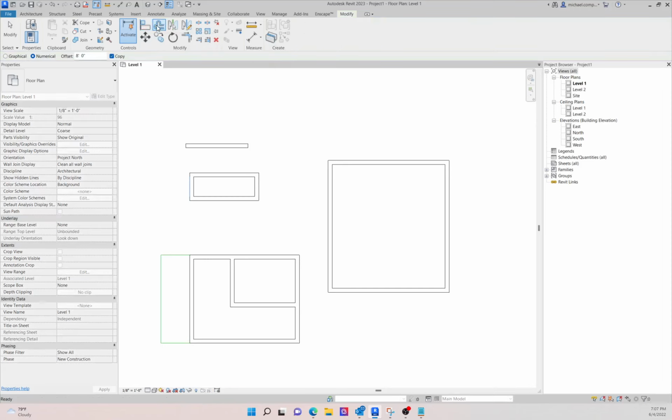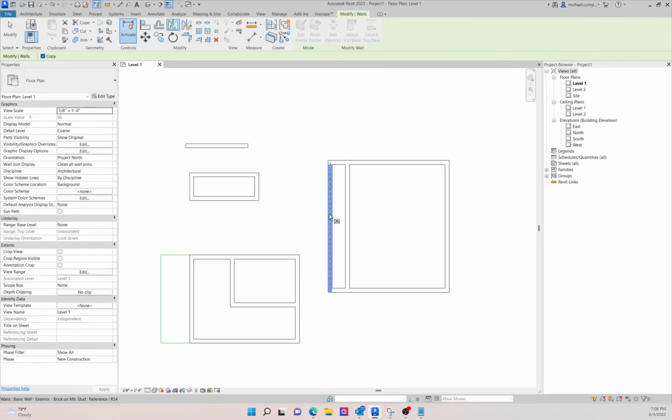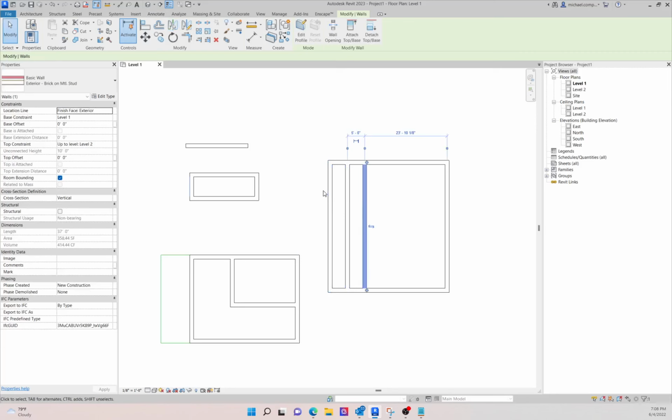There is an offset tool. I give it a specific dimension, let's say 1 foot. I'm sorry, I have to change the offset settings. Okay, so I changed the offset to be 1 foot. Actually, I'm going to make that 5 feet. Okay, so 5 feet, and then it offsets 5 feet. I can do mirror along a specific axis. So if I wanted to take this wall and mirror it along the center axis of this wall, it puts one exactly that distance away, which is super helpful.